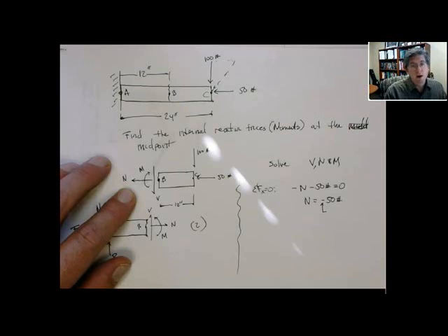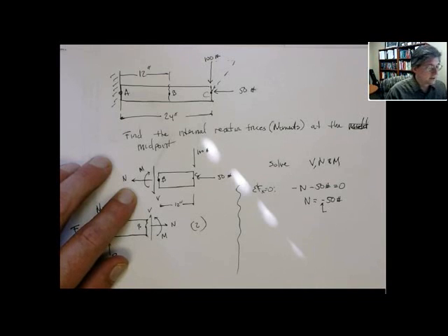If you're good, maybe more complex problems, you can figure it out by inspection. But as problems get more complicated, it's really difficult to correctly pick the orientation. Why waste your time doing that? So what I recommend is not trying to figure out which way the internal reaction forces should go. Just draw them on the free body diagram and then solve for them and be careful about the signs. That's all you need to do.